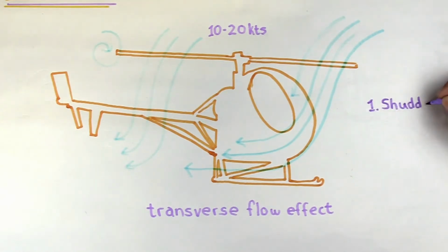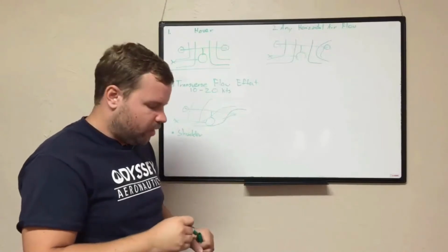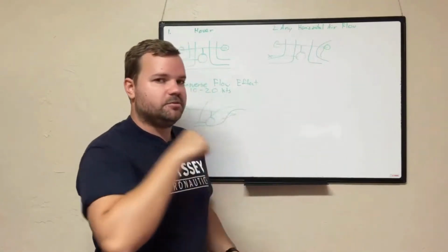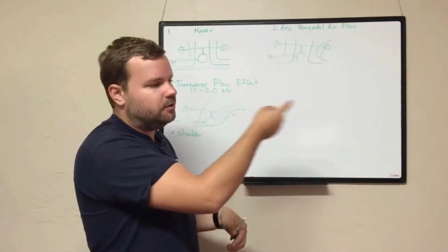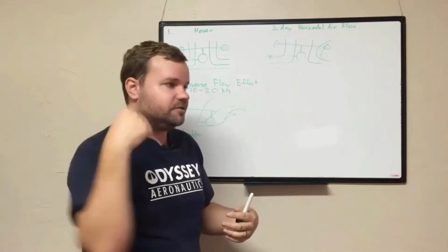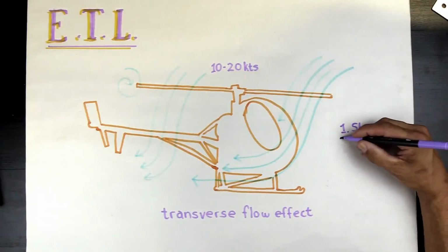And you'll recognize this as you start flying. You start taking off and you get a little vibration, a little shudder. What this is, and the way I picture it is, you have a blade and it's going back and forth between, oh, clean air, my vortice is blown away, I got good horizontal flow, not as much induced flow, oh, bad air in the back, I got a lot of induced flow, I got a vortice, not producing much lift. So clean, dirty, clean, dirty, clean, dirty. It's just the vibration of the rotor system going through that.